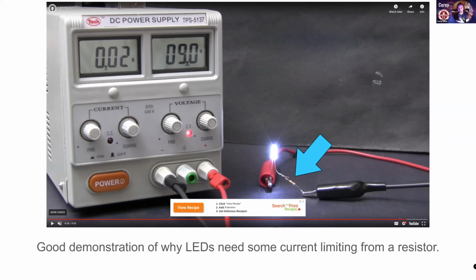So that's the sort of crude, quick attachment that you could do if you're trying to test and see if it's pointed the right direction. I've done a lot of sanity checks where I set up a wire and a resistor attached the right way, and then I can quickly just touch the LED to it, not because that's what it's going to be in my target design, but just to check and make sure, okay, am I putting this in forward or backward? Because sometimes I lose track, I've snipped maybe the lead, so I don't know which one's longer, and the epoxy on top is opaque, so you can't see in.